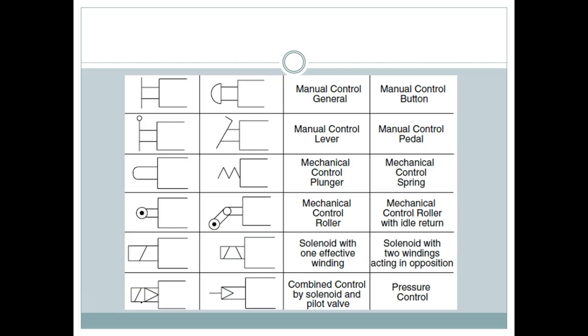So just about all the valves over on our line over there, and I've got one, by the way, that I can hopefully bring over here. We've got one where the solenoids have burned up on them. We leave our robots on 24 hours a day, and what's happening with these two-position valves is that normally to keep it in one position, you have to keep pressure on there all the time. So the solenoids are staying on 24 hours a day, and they should be able to handle that, but undoubtedly, when they put those valves in there, they didn't choose one that would run forever.